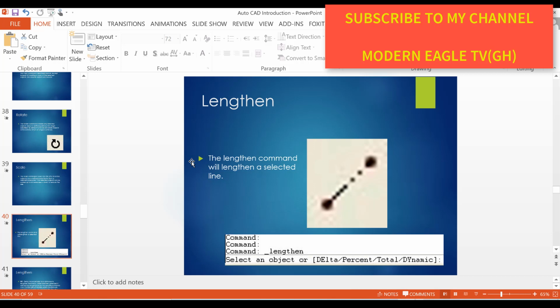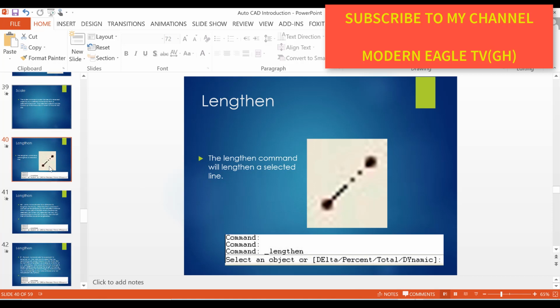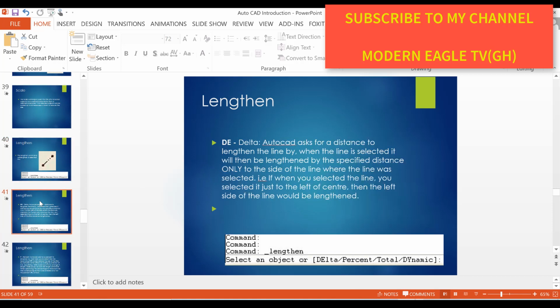The lengthen command will lengthen a selected line. Delta: AutoCAD asks for a distance to lengthen the line by. When the line is selected, it will then be lengthened by the specified distance only on the side of the line where the line was selected. That is, if when you selected the line, you selected it just to the left of center, then the left side of the line will be lengthened.